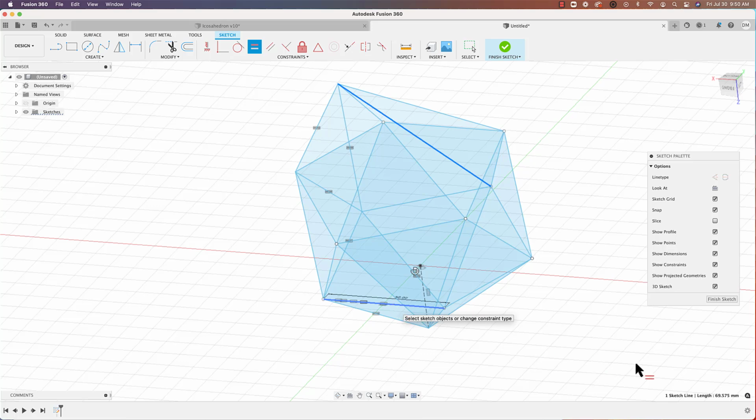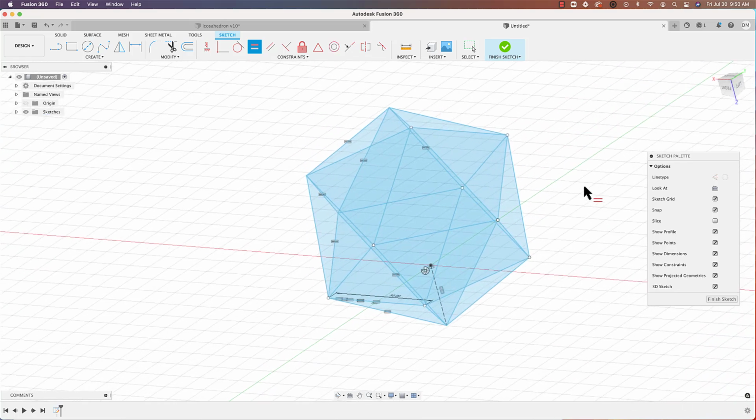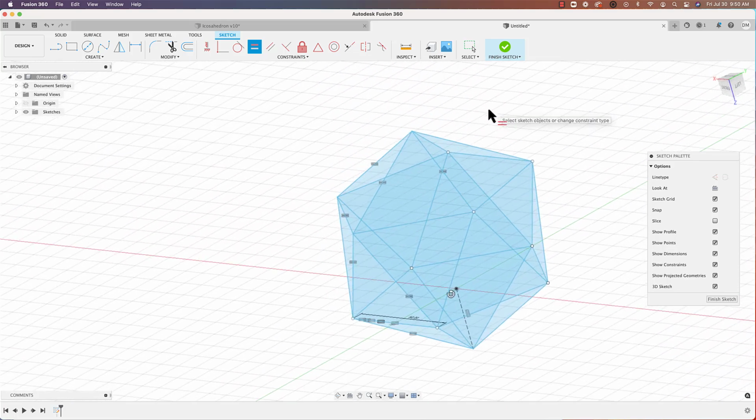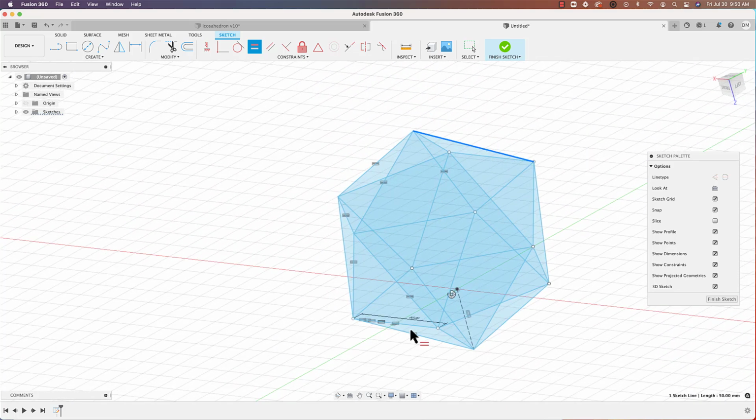But you'll also notice that you'll get an over constraint if you try to do one more. So right there I can tell that looks to be good, but I'm going to try one more just to be safe and sure. You can see the wheels are spinning right now. It's trying to do that calculation, and I can tell from how long it's taking that it's going to tell me that it is over constraint. So give that a couple seconds, and there's the error: sketch geometry is over constraint.